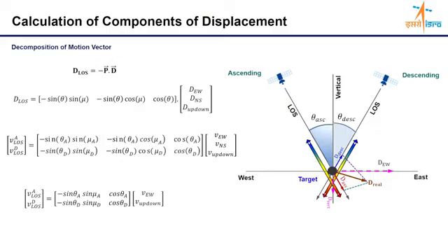So you can say we are able to calculate only the two-dimensional displacement vector of the deformation, not the three-dimensional deformation. Here east-west is the x component, and up and down is the z component. So the actual deformation vector you can write as: actual vector equals displacement along the east-west times the unit vector along the east-west direction, plus the up and down displacement component times the unit vector along the up and down direction, which you can consider as the z direction also. Whatever you like, you can consider it. Now try to understand the limitations of InSAR.